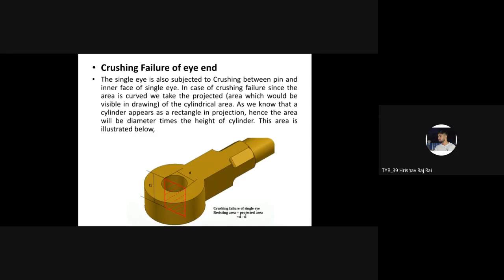But in some critical applications, in machineries where these knuckle joints are used, we replace the total knuckle joint if elongation or wearing of the pin as well as the single eye or double eye takes place. For example, in suspension of vehicles, this knuckle joint is used. If those parts wear out, noise is generated because of that part, and hence it will get replaced.